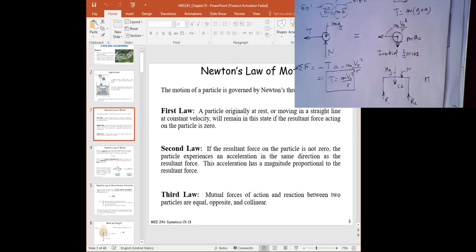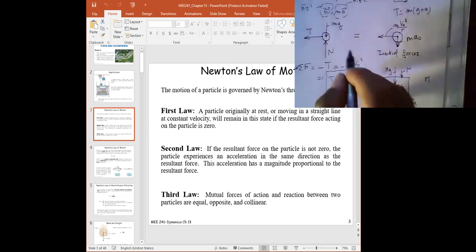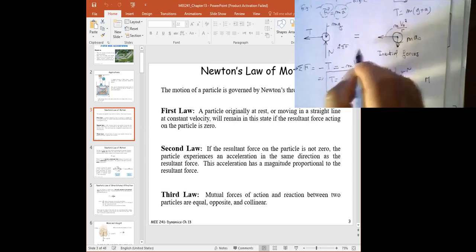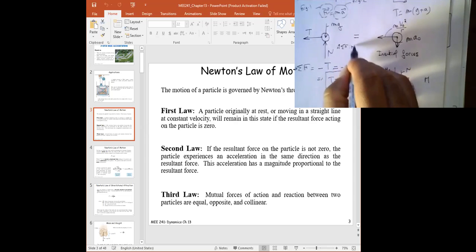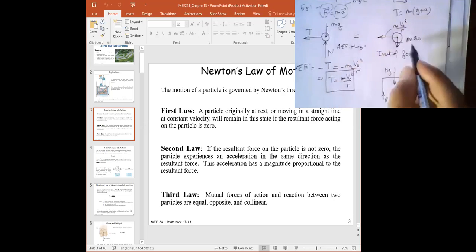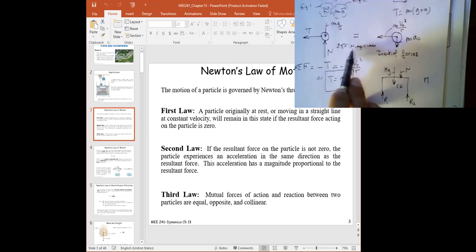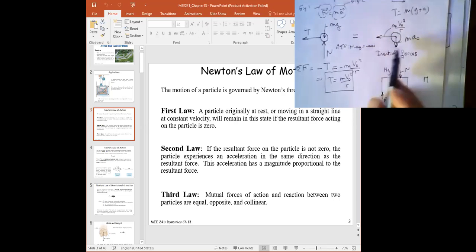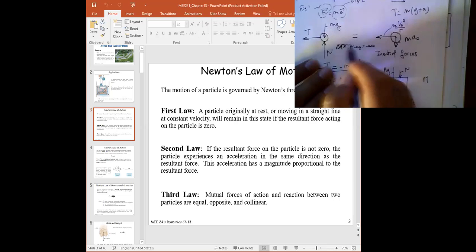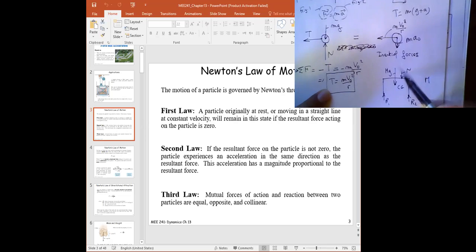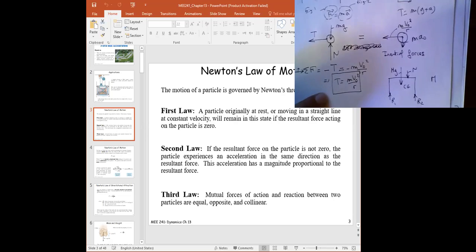If we sum the forces, we have ma on the other side, and so it won't be equal. Exactly. So this is how you want to be very careful, right? If I sum the forces in the vertical direction, I want to have N minus mg equal to what? Minus ma0. So a0 is interfering, and N is no longer equal to mg now, because I have accelerations here. So what I want you to understand is to just keep N as an interaction force. You put it on the table, and then you put it here, and then you just continue your analysis.